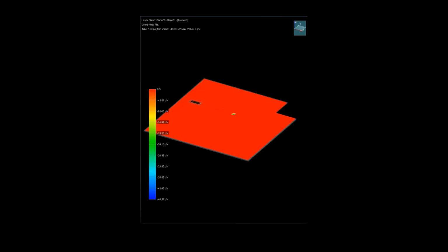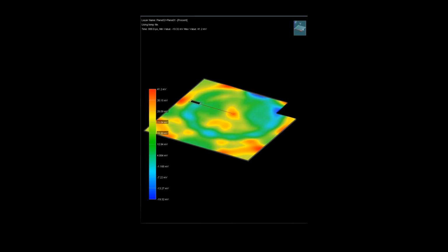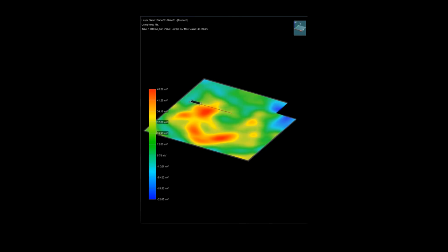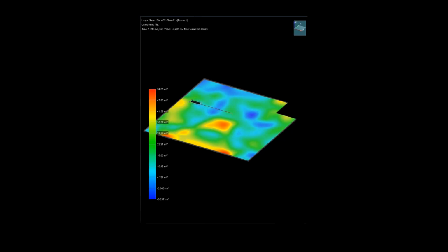Electromagnetic fields on PC boards exist between any two conductors, such as a microstrip over a return plane. Current flows in loops and must have an uninterrupted path back to the source. If this return path is broken, the electromagnetic field will latch on to the next closest metal and will not likely be the return path you want. It will leak throughout the dielectric and cause common mode currents to flow all over the board, as well as cause cross-coupling of clocks and other high-speed signals.